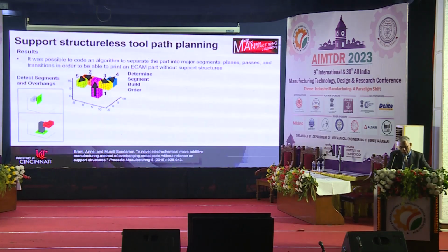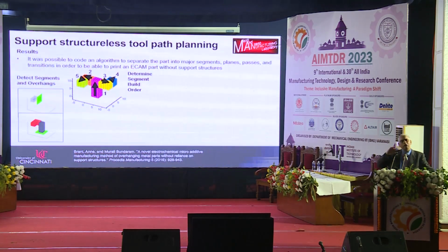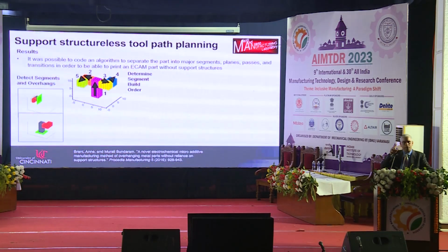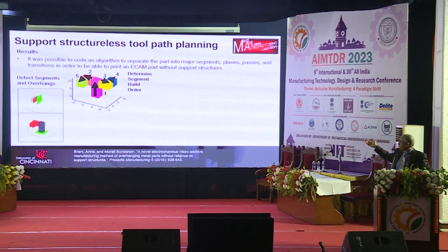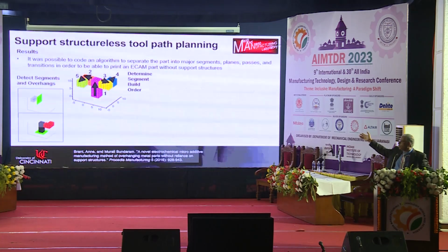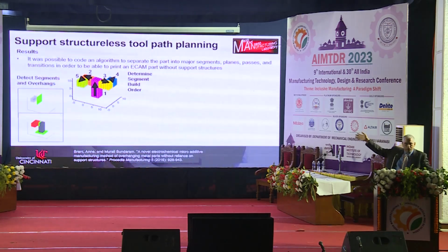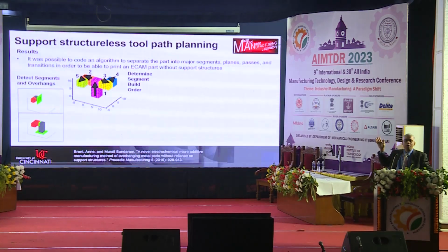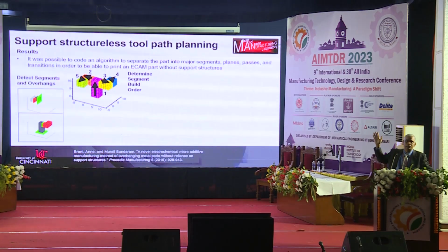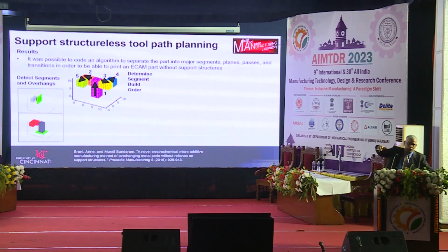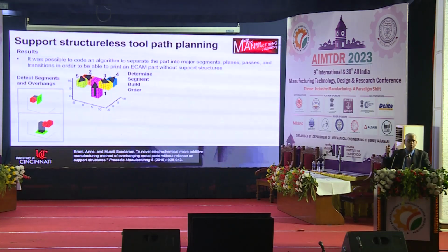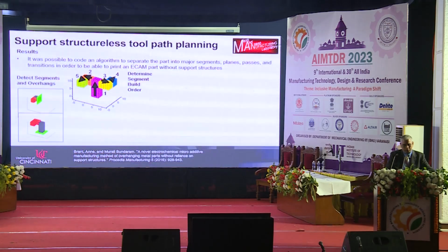So these type of logical things, again I repeat, is not the only way of doing it. Whatever I am showing you, the problems and what I did, is just one way. You can come up with some other way. For example, you can say I am going to do the 2 and then I will do the 5, because I will finish everything on one side, then I will come to the next side. You can think like that. I did not do that because then the centroid will get shifted, so my structure can topple, right? So for me the criterion is balancing, so they keep the CG at the middle. So I used this particular approach. There can be many other approaches.